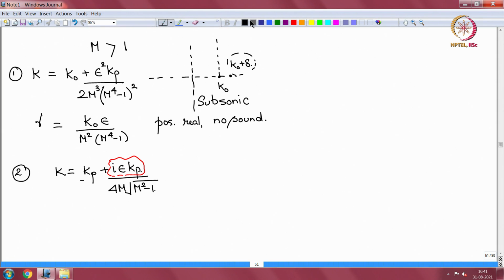Then gamma, let's see where it is. This is my k0 cut, it's here. So this is a propagating root on the plate, but it also decays slowly. The decay depends on the amount of damping you have. This is positive x direction.